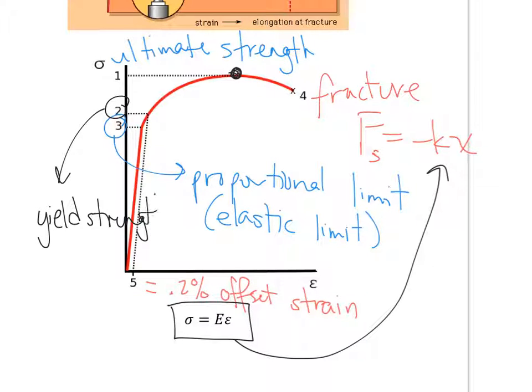We call it the yield strength because this is when it begins to yield. It begins to stretch uncontrollably. It's like when you take a slinky and you pull on it, and one person pulls on one end, one person pulls on the other. If you pull hard enough, what's going to happen to the slinky? It deforms permanently. That's what this is. Yield strength shows where it starts to permanently deform. Where that curved region is, this curved region, is when it's actually deforming.